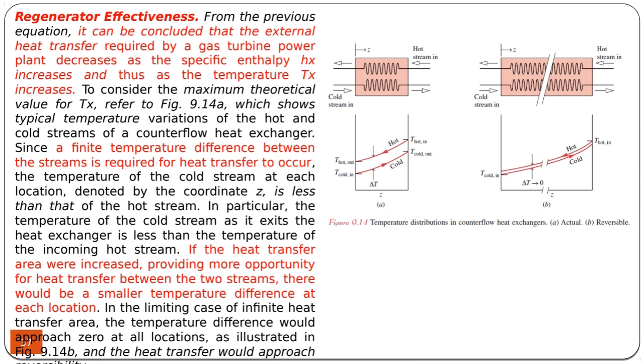Then in this case, the hot fluid, which is the exit of the turbine, is transferred to the cold fluid, which is the exit of the compressor. And as you can see, there is a temperature difference between the hot gas and cold gas.